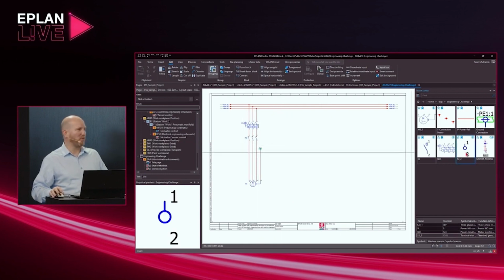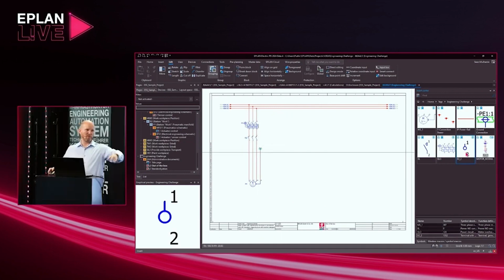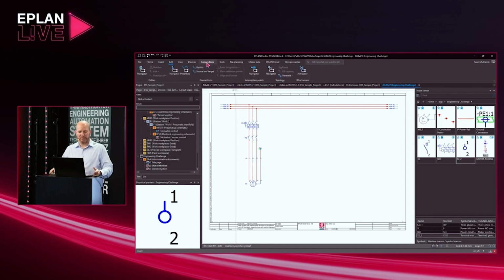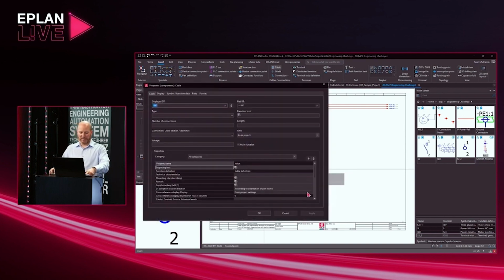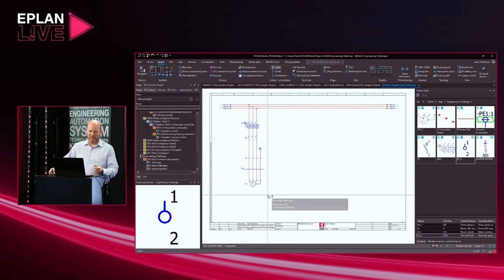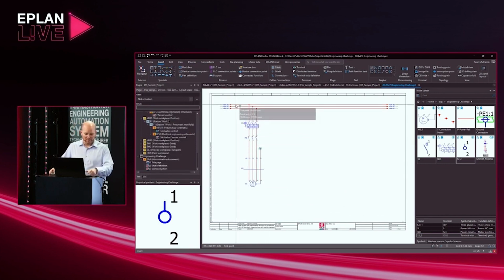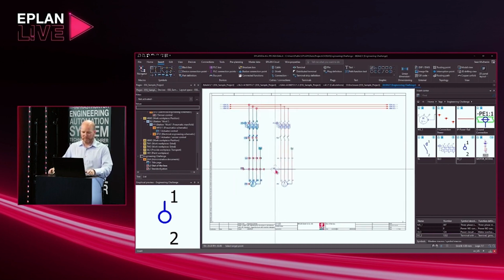And now I'm going from the cabinet, we talked about terminals, out to the field, so I'm going to drag a terminal strip across here. And of course, we need a cable, so I'm simply going to add a cable onto my drawing. And here we go. My first part of the design is completed. So here's a very simple motor starter circuit, but as you can see, it's easy to just drop the symbols and place them. And if you need two of them, just highlight it, duplicate it, and then move it across.